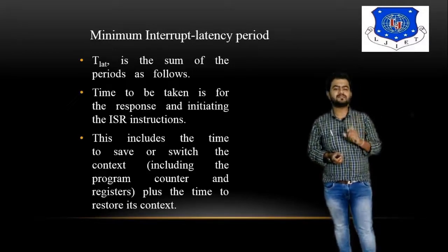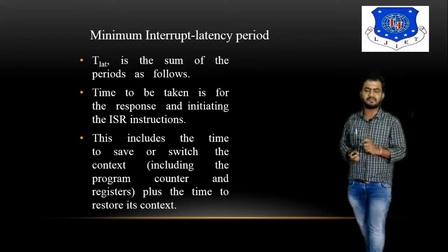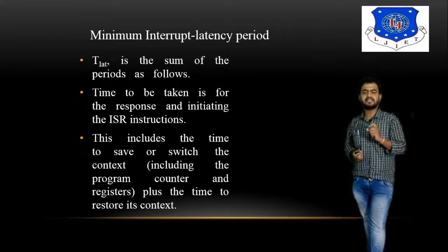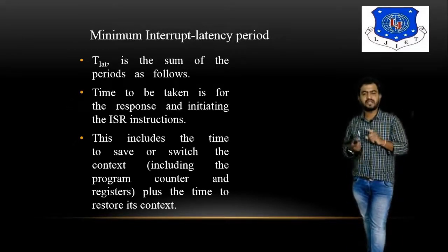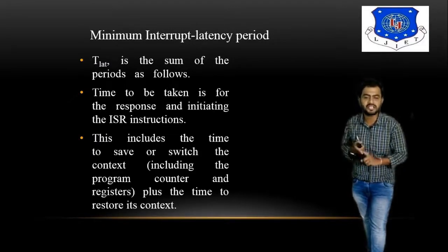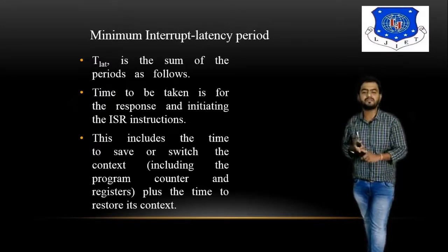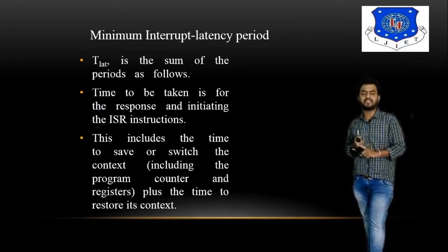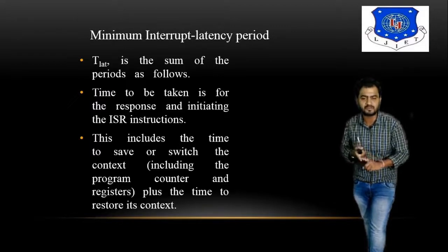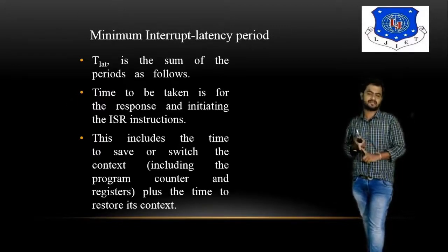Minimum interrupt latency period. Now, what exactly is the meaning of the minimum interrupt latency period? T_LAT is the sum of the following periods. The time taken to respond and initiate the ISR instruction. This includes the time to save or switch the context, including the program counter and registers, plus the time to restore the context.